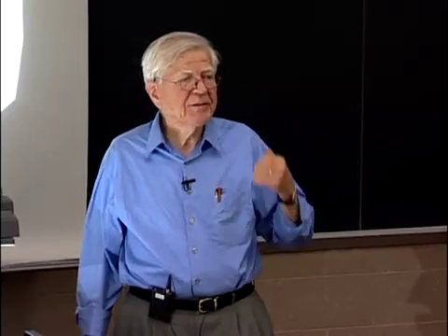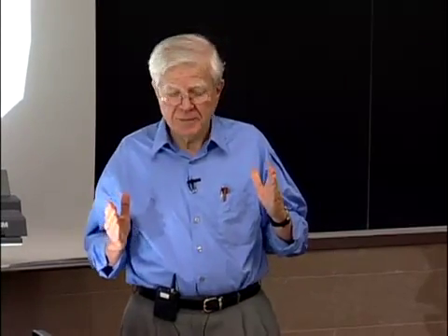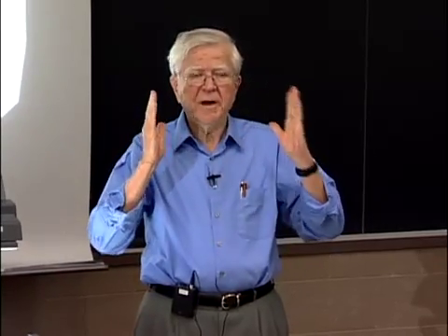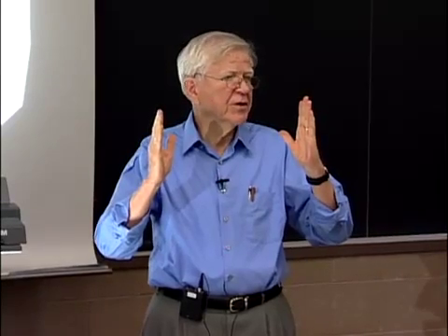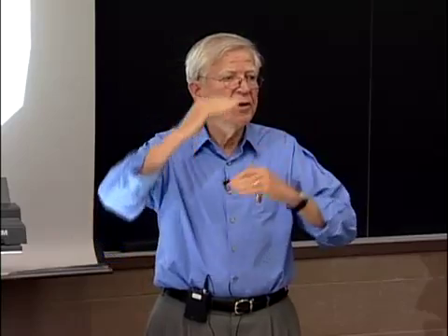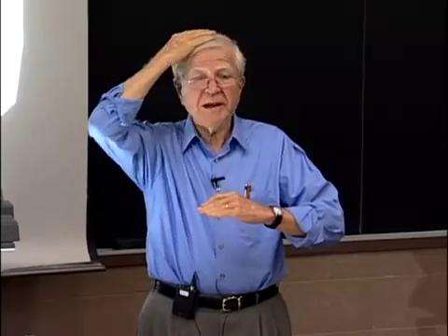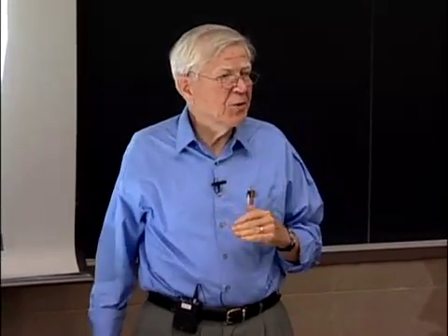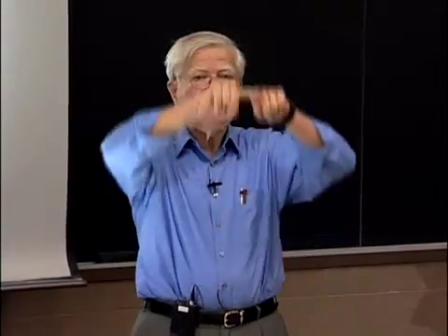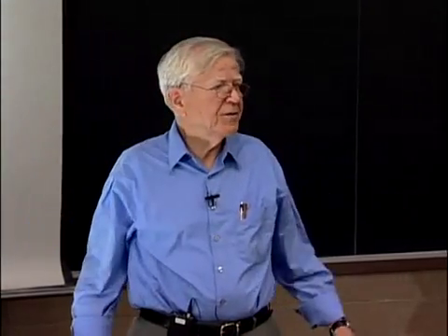So this particular set of prolate spheroidal functions gives you the answer to the following question. I would like to find that function which is limited to minus t over 2 to plus t over 2, which has the largest fraction of its energy within the band minus w to plus w. What is that function? Well, that function happens to be this zero-order prolate spheroidal function. It's the nice property that it has. And it's a nice function which almost looks like a rectangular function, but it just trails off to 0.